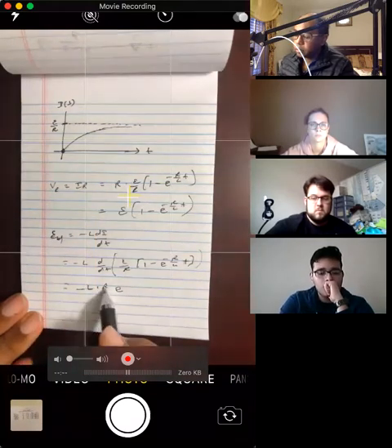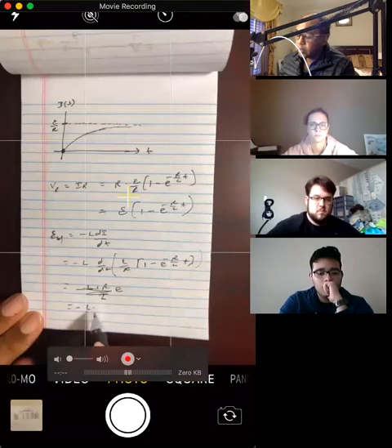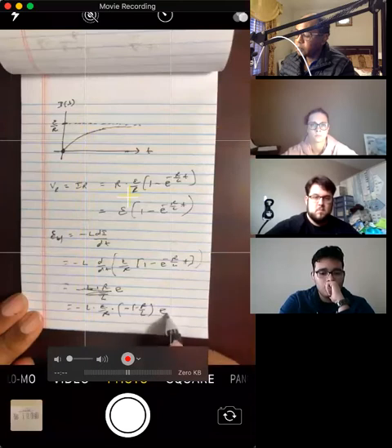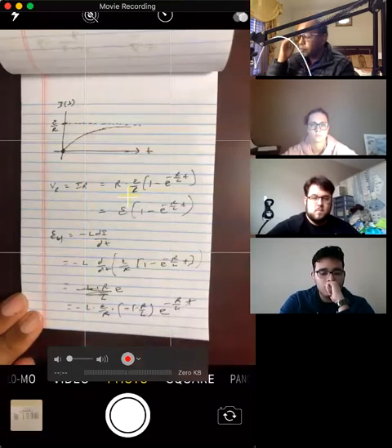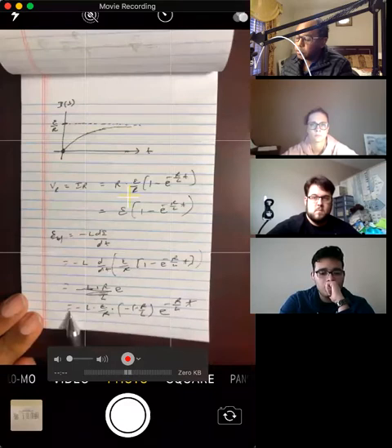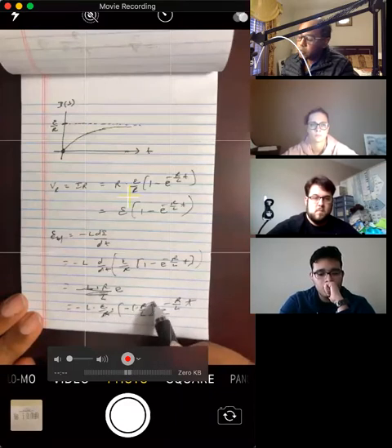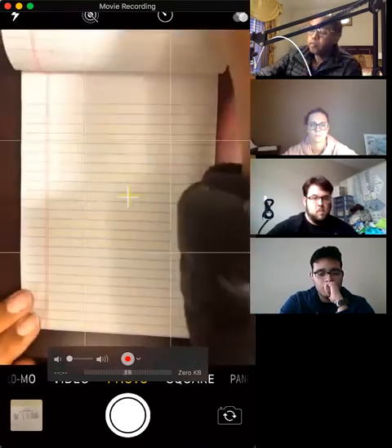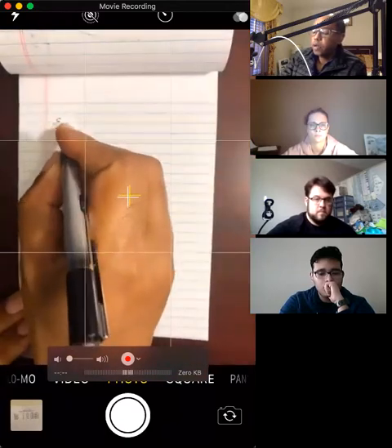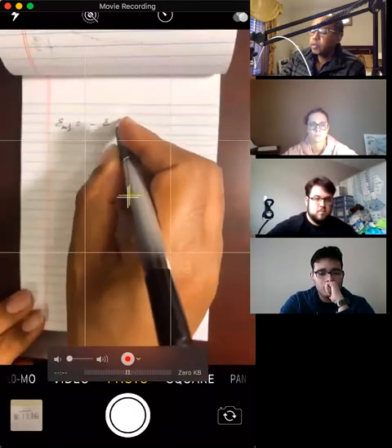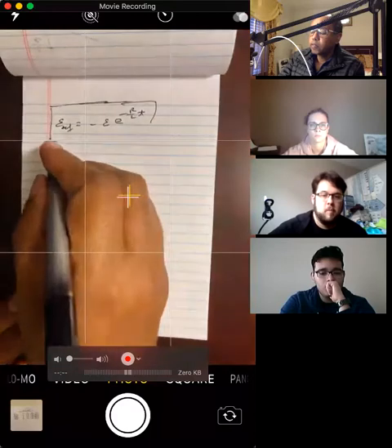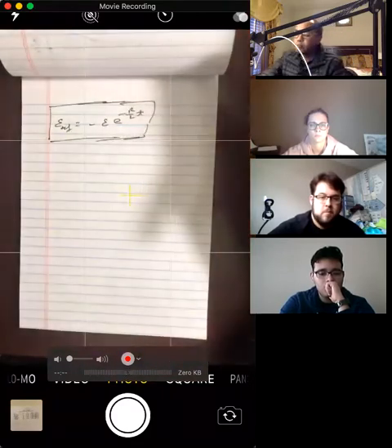So again, you've got negative L, E over R, and when you take the derivative over here, you get negative R over L like this, and then e to the negative R over L t. So you've got positive over here, so this is going to be negative. You've got resistance going away. You've got this one going away. So it's just the negative of the EMF. So this self-induced EMF in the inductor is negative EMF times e to the negative R over L t. So this gives you the self-induced EMF in the circuit.